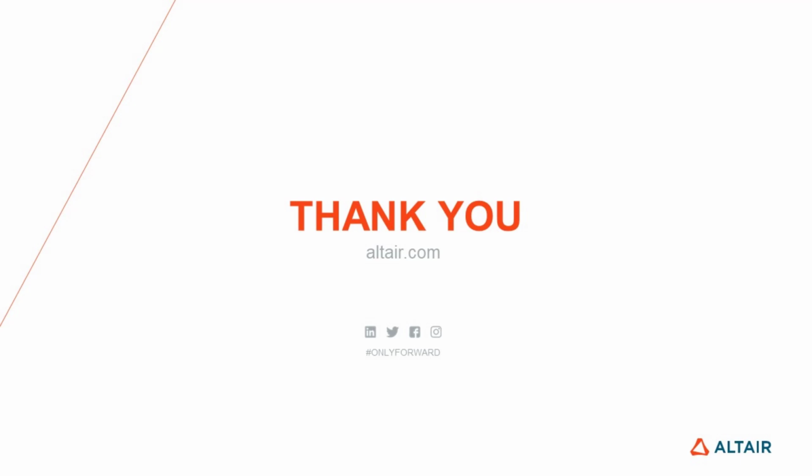Thanks, Salim. Just to add a couple of small things, to add to what Preetam mentioned and also what Salim has mentioned throughout the presentation. One of the things you can use now in Sketcher is, if you do convert to FE geometry, you can then use that base FE geometry in Sketcher. That will also help in any of the sketches you want to do on a legacy deck. You can effectively generate the geometry from the mesh directly and then use that geometry in Sketcher. So it's some really good linking together coming through from that.